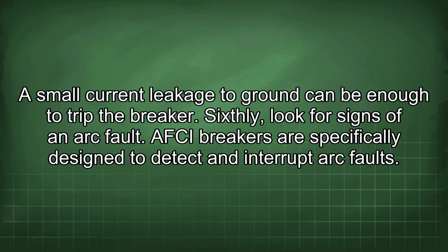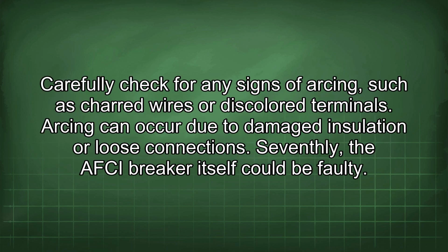Sixthly, look for signs of an arc fault. AFCI breakers are specifically designed to detect and interrupt arc faults. Carefully check for any signs of arcing, such as charred wires or discolored terminals. Arcing can occur due to damaged insulation or loose connections.